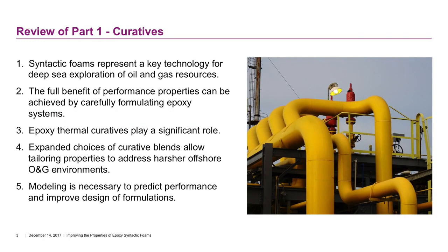So this is the full review of Part 1 with regards to the conclusions that we found. The first thing, obviously, from a deep sea exploration standpoint, is that syntactic foams represent a key technology and play a key role here, specifically with regards to transport efficiency of the crude reserves. Epoxy syntactic foams, which have been utilized for some time, require that we take a fresh look at them with regards to how they're formulated. We can make some slight changes and create some very different results, as we have begun to discover.